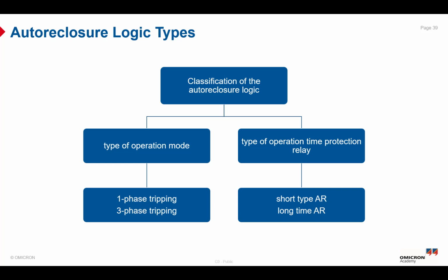After each AR shot or AR cycle, the circuit breaker needs enough time to recover, and for this purpose the relay starts the so-called reclaim time. After the final close command, during this time the AR is not ready for any faults that occur, so the relay trips in the regular distance schemes. Once the reclaim time has elapsed, the relay allows a new AR cycle or AR shot. So it mainly depends on the time needed for the circuit breaker to perform a new auto-reclosure cycle.